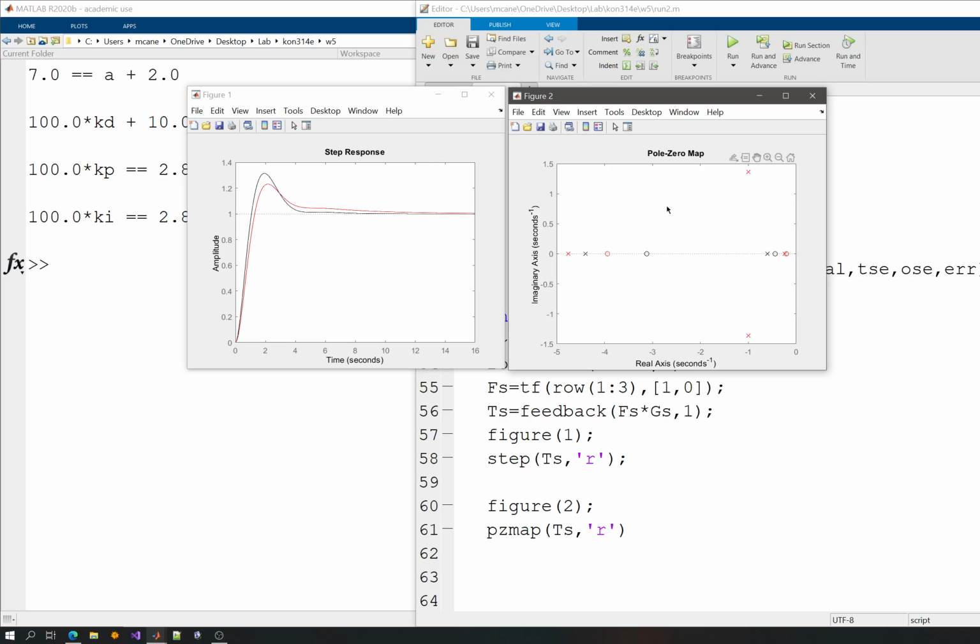setting time. And also this pole zero map will look better and better, and hopefully this zero will not enter the dominant domain. So these are a little bit far to the left, and I have a pole zero cancellation near the origin, which is not that ideal, but somehow does the job. The black one has a not that ideal cancellation, and I can see the effect that the system becomes a little bit slow here, has more overshoot since we have a zero in the dominant region, etc., etc.